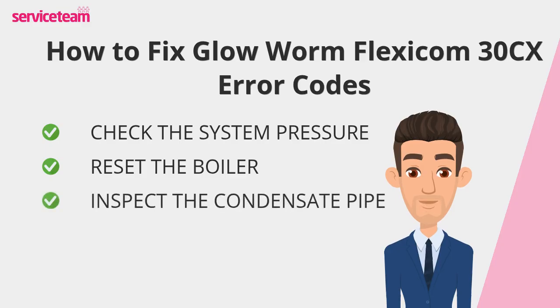In colder weather, the condensate pipe outside your home can freeze, stopping the boiler from starting. Check the pipe for ice or blockages, and if it's frozen, pour warm water over it, never boiling water. Make sure the pipe slopes downward so the water can drain properly. Insulating this pipe can help prevent future issues.